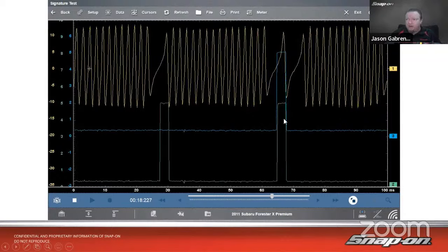So the cam sensors definitely need to line up like that on this particular car. Now, a nice thing about this too is the manufacturer actually publishes a known good cam crank correlation pattern. Not every manufacturer does, but many of them do. If you go look inside a cam sensor code diagnostic chart, oftentimes they'll give you those in there. Sometimes it's just published as a cam crank correlation chart. But good to know, judging by timing.